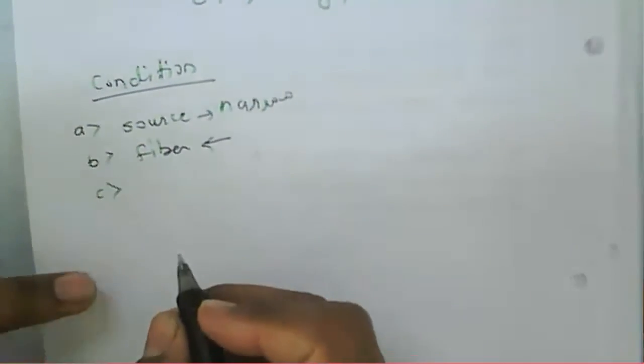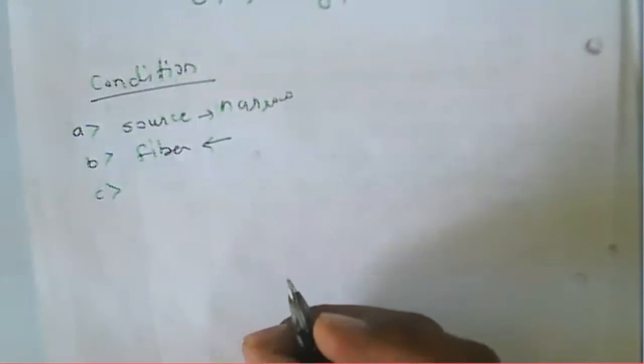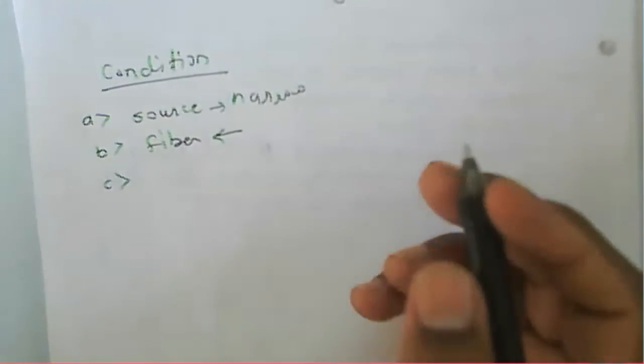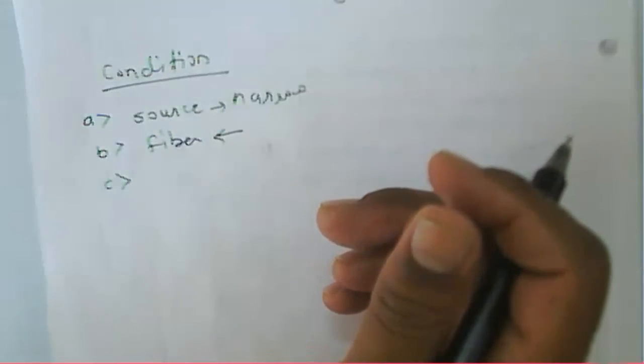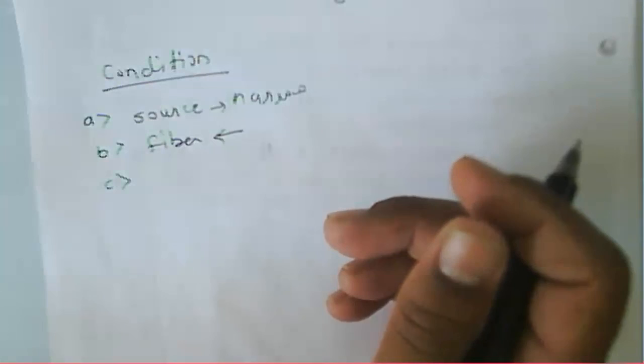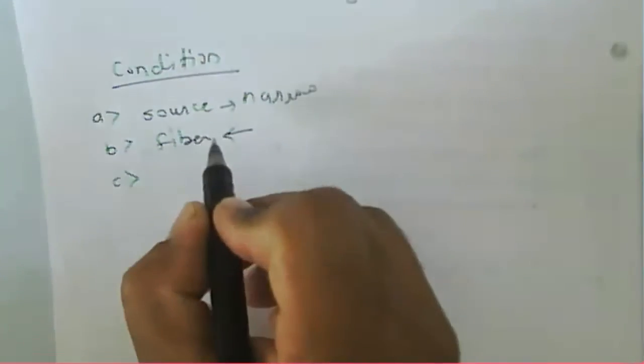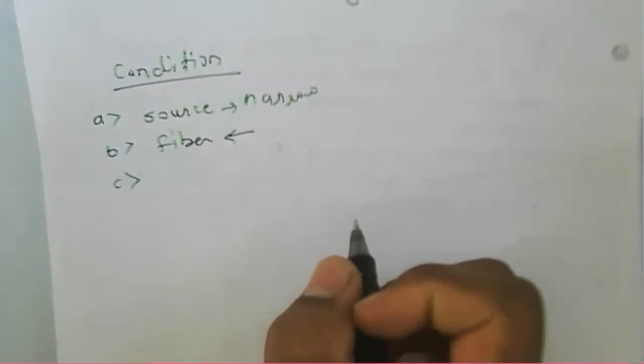So that is about modal noise. Generally we say a single mode fiber doesn't have it, because a single mode fiber doesn't support a difference in modes. But in a single mode fiber, modal noise can be present because it supports two different fundamental modes, with different polarizations.